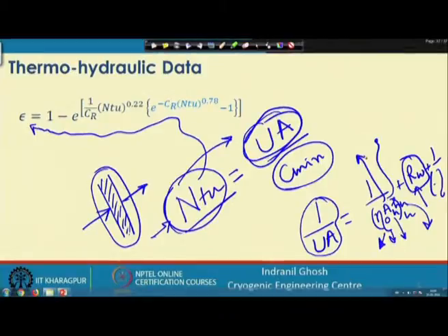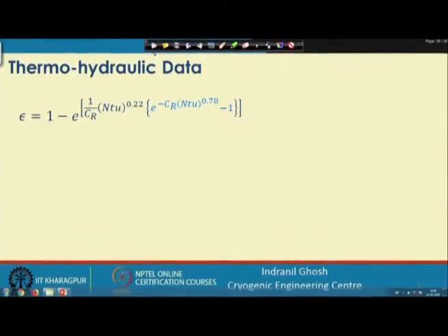First of all, we need an idea about how many layers of air and gas streams there are in this particular heat exchanger. Once we know the number of layers for the gas and fluid side, we have an idea about the heat transfer surface area available for the gas side as well as the air side.